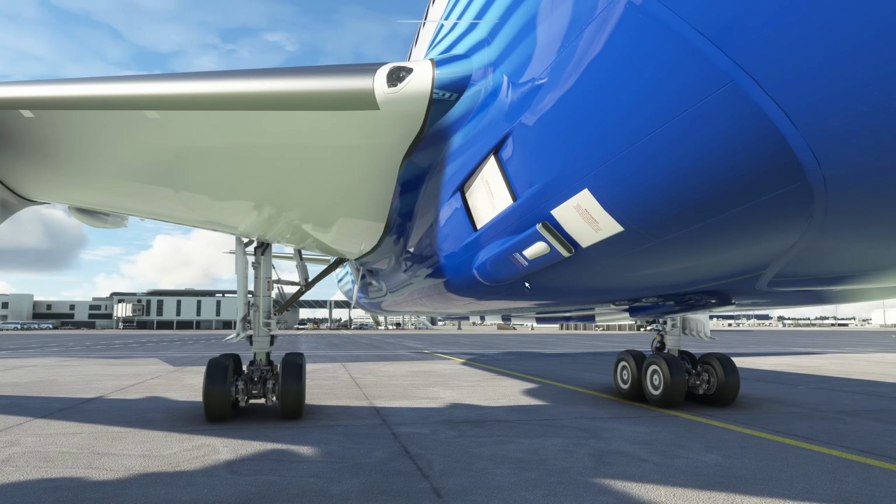Now, what we have is the inlet for the cabin air compressors, or CACs. There's 4 on the 787, 2 per side, and then what they do is they effectively act like a compressor in the engine, but they are their own separate system. So they suck the air in, squeeze the air, and then it can be used straight away as if it had come from the engine, as if it was bleed air. So that squeezed air is then sent just the same way to an air conditioning pack, a separate system, and that is where it is cooled down and sent into the cabin.